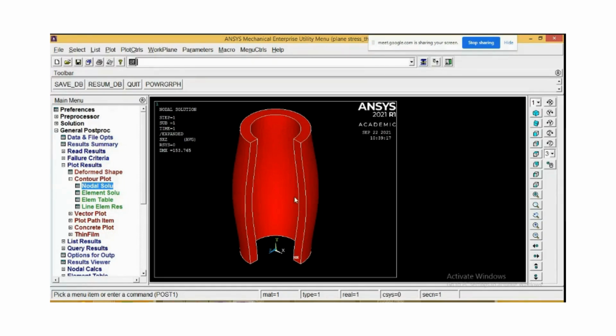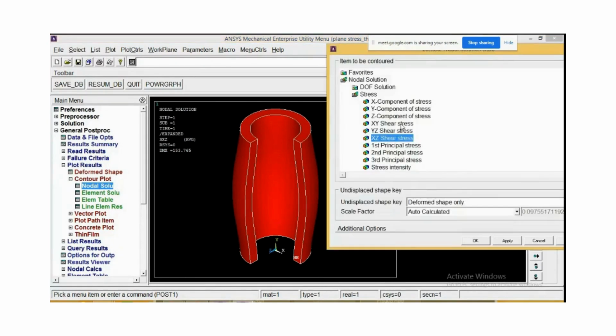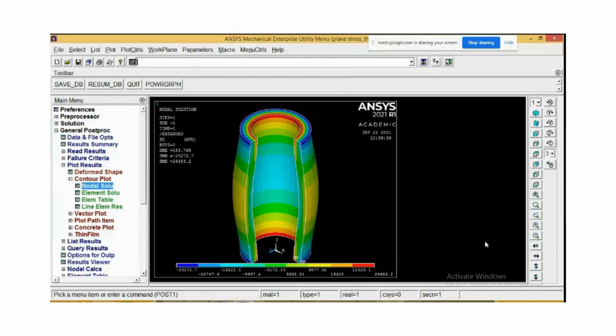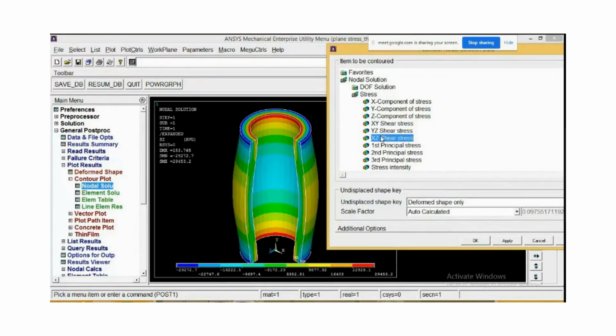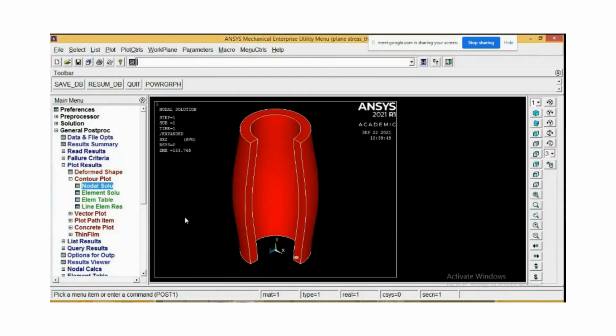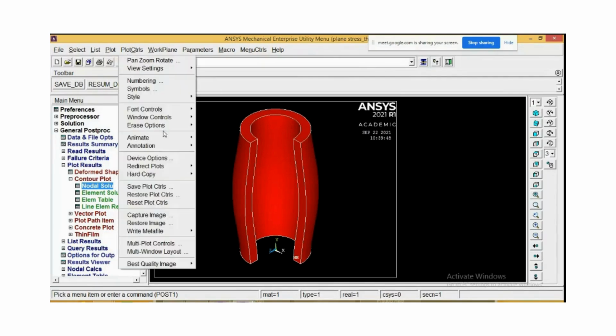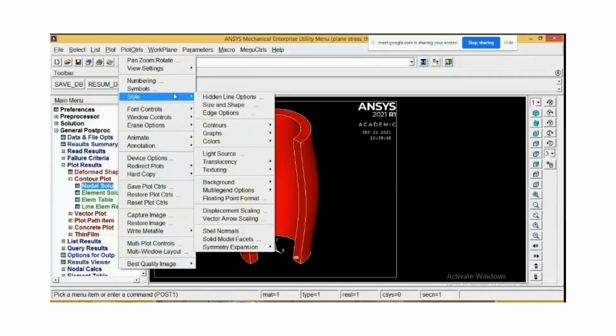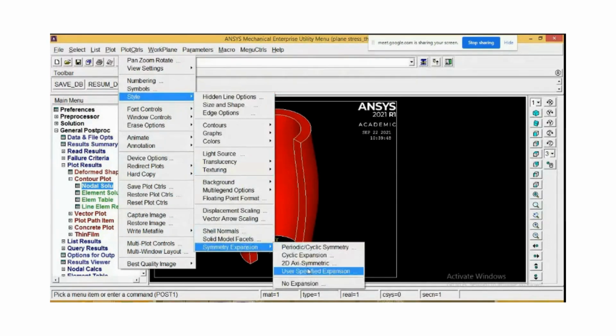So stress in that region will be 0, stress in that plane will be 0, shear stress, right? We are getting the displacement because of the nature, actually it must be zero theoretically, but we are not getting that z component. But the shear stress you can observe, the yz and xz components are all zero, you don't get any value here, you don't get any value here. So this is the way you can evaluate the result for the pressure vessel.